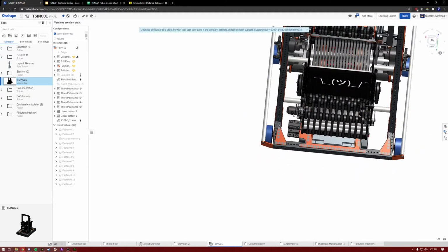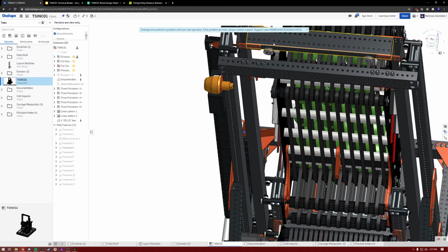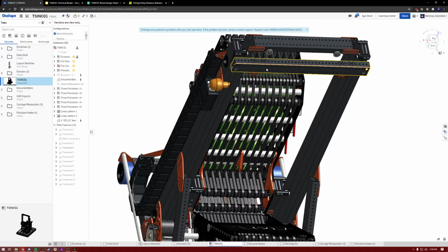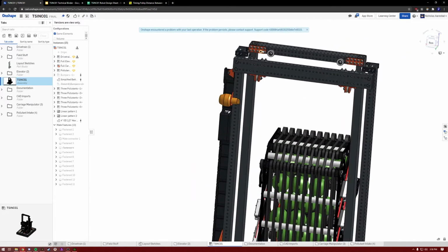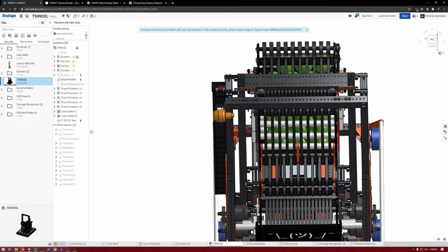The biggest design mistake on this robot is probably this rigging. I'm not confident that this rigging would actually work in reality. It's just really tight around this. What I wanted to do, a little bit into this, was redesign this to do an internal belt rigging, like 2010's 2018 robot. All right, so that's about the design of this robot. In another video, I will talk a little bit about some of the CAD techniques about it.